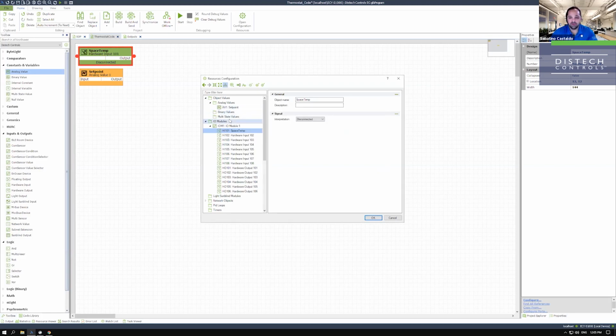And that's important because the controller will use a dynamic resource allocation. It'll create an object once you've added it. It'll exist. If it doesn't exist, you will never see it. So if I were to discover this controller, discover its points or create points, etc., I'm only going to create what I've saved, what I've brought into the controller. If I've brought in points and I didn't use them, you may get a lot of points that aren't doing anything in your controller. You may want to revisit this and remove all unused resources. And it's normal. It happens. We often play with certain items. We forget about them and we never go back. But it's a good code cleanup. So it's a really useful tool to do that.